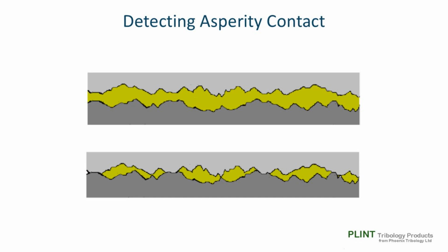It will be obvious that each asperity is in effect an individual switch, so just one asperity coming into contact will be sufficient to produce a short circuit. However, we may have many more than one asperity in contact. In other words, we have multiple switches in parallel. There is no way of telling from the contact resistance measurement how many closed switches there are. It could be 1, it could be 100.